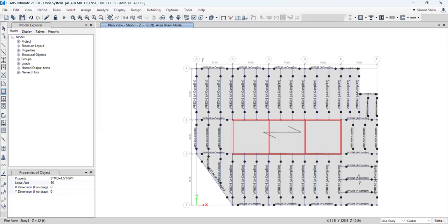So you see that for most floors the slab metal deck orientation should be running perpendicular, left and right, but if you happen to frame in a different direction, you need to segment it and draw it separately so that the metal deck is running in the opposite direction. Okay.